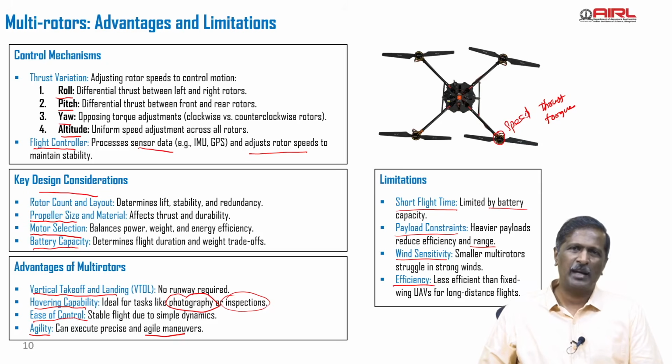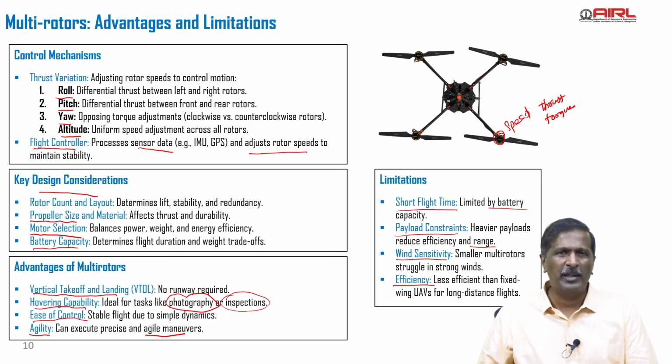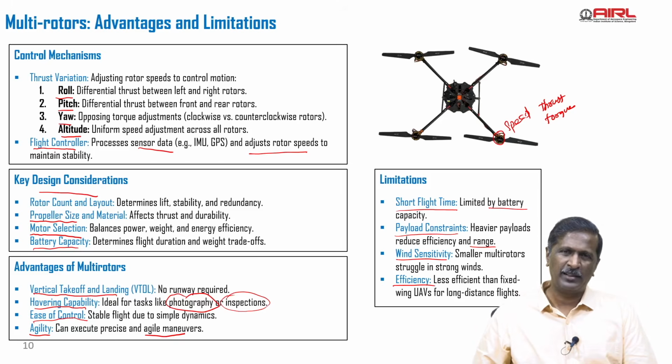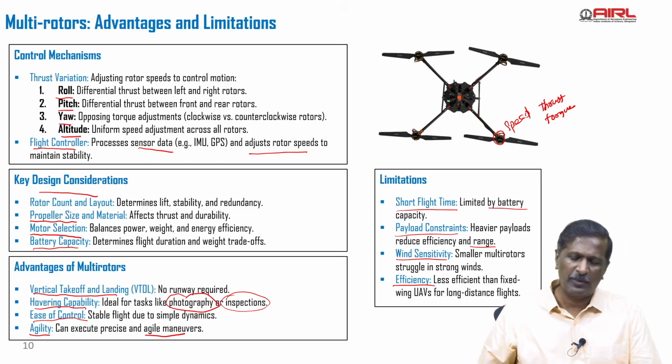A fixed wing aircraft has the ability to generate lift because of the wing being present, and that wing helps you achieve high speed operations too, right? Here the lift is produced by the thrust which is coming from the motor, right? And the motor orientation, the speed at which we are rotating, will also help them to navigate in space. Their efficiency is also a factor, right? We look at the motor, propeller, as well as the battery combined together, and the speed controller which controls the speed at which the motor is going to spin. All that affects the overall performance of the aircraft.